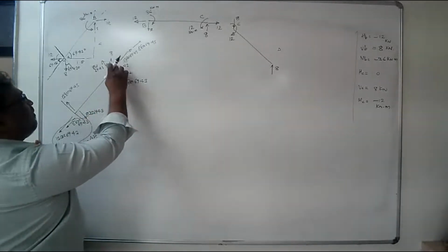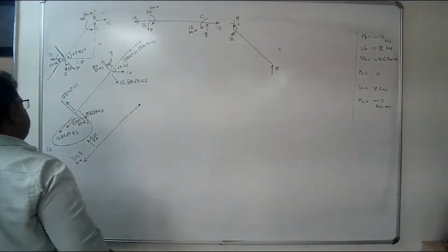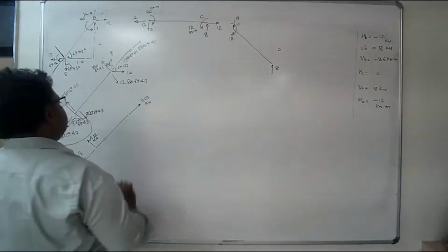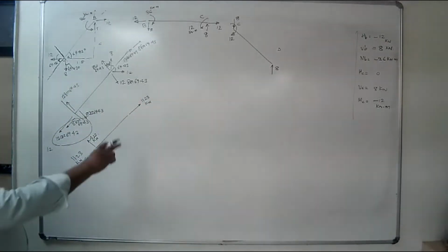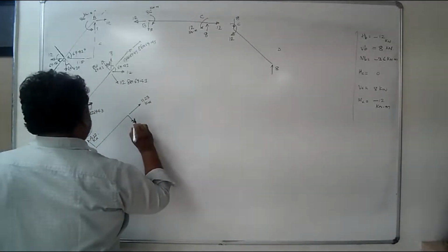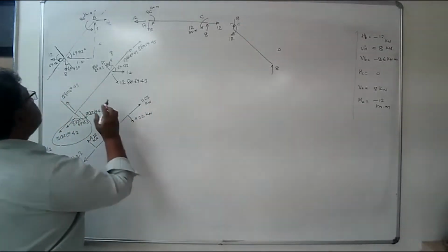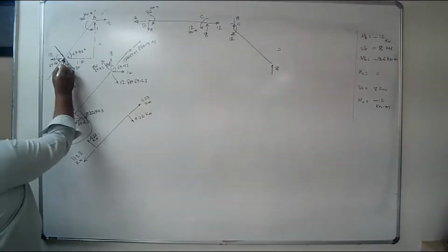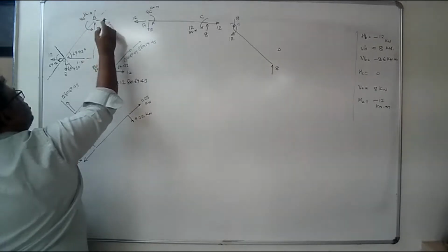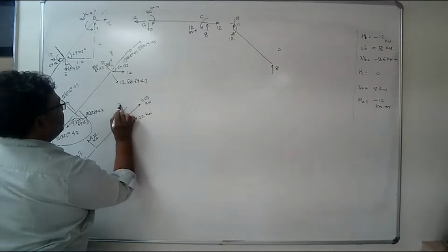What about here? If I resolve these two along, again it will be the summation, so it will be the same thing. This will be equal to 11.23 kilonewton. And then here, this will be greater and this will be smaller, so now the shear force will be acting down here, and that will be equal to 4.22 kilonewton. So the forces which were acting vertical and horizontal are resolved along and perpendicular. And here a couple will remain as it is. So this is the couple 36.